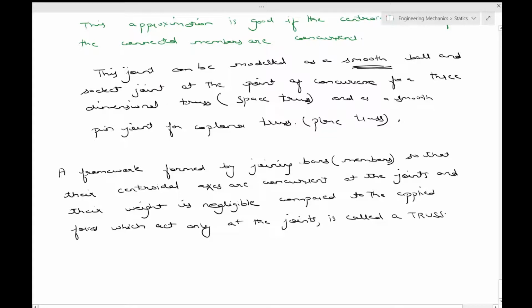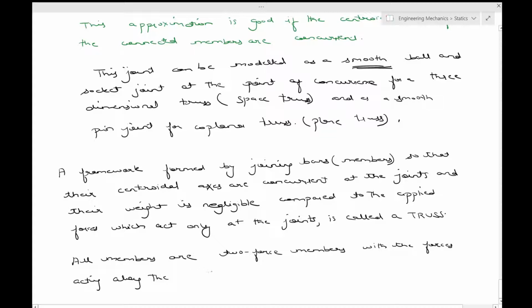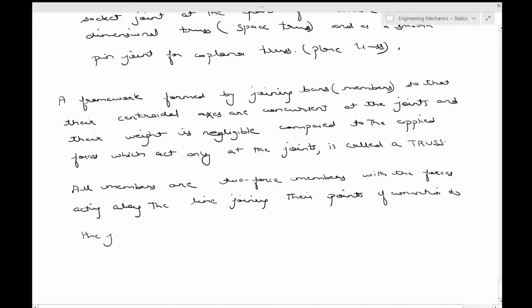Okay. So this implies that all members are two force members with the forces acting along the axis or the line joining their points of connection. Okay.